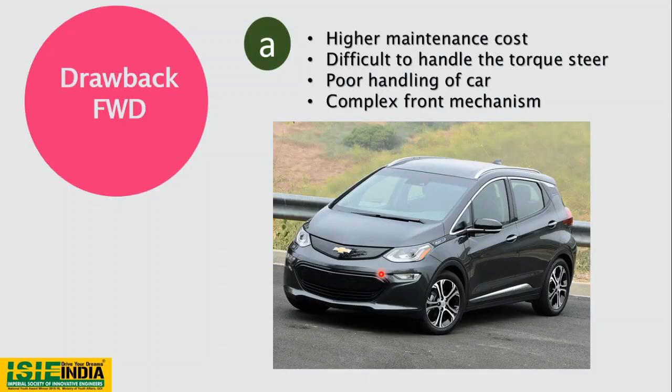as everything has some advantages, it also has disadvantages or drawbacks. So it has higher maintenance costs, because there are things such as the differential placed there, and we have complex steering mechanisms which are due to the packing of the whole front hood, right? So it becomes quite difficult, and there is a lot of maintenance involved in it. This is one of the major drawbacks.